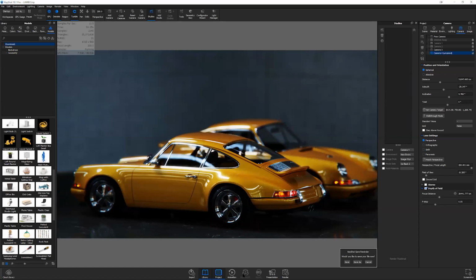So it had the same composition in the frame, the same materials, the same lighting, the same shadowing, and the same scaling. We were able to do that with hundreds of CAD models, and by the click of a switch, selecting all the CAD models we needed, we generated new, fresh KeyShot files for each of these products. Then we did a small, quick render of each one so we could check it off our list, making sure the files were all set up correctly, the product is in the right orientation, the materials are applied, and